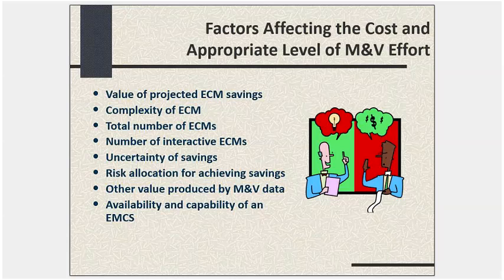If you've done a good job of defining operating hours and you've measured pre and post kW and accounted for diversity and things like that, that's not too complicated. That's much less true of a central chiller plant, which might have a very diverse operating set of parameters and may require a more complex strategy and a bigger investment in M&V.